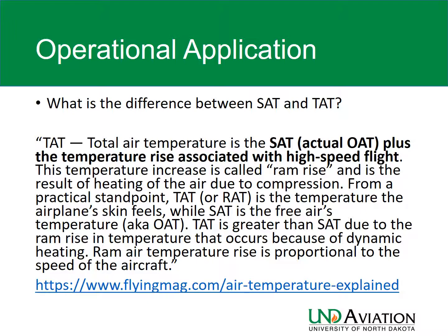Another topic I wanted to talk about, because it's not common in the small GA world, because we're not typically going 300 knots or 0.8 Mach in a Cessna. Pretty uncommon. Is this idea of static air temperature and total air temperature. So this definition I thought was fairly concise.